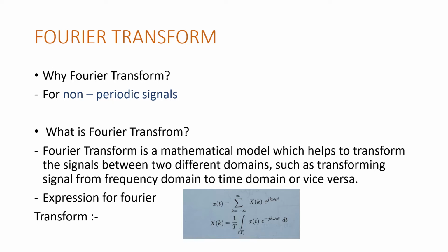Again, the question arises, why only Fourier transform? Why not Fourier series? Because Fourier series is only applied to periodic signals but not non-periodic signals. In order to convert non-periodic signals into the frequency domain or the time domain, we need to use Fourier transform, which is more flexible.